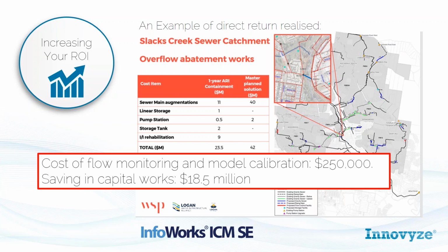Yep, thanks, Patrick. So I guess I'll just rewind a little bit. Queensland is a little bit behind the rest of Australia and the world. It traditionally has been, and the approach to sewer planning and network analysis has been based on the traditional peak wet weather flow approach. So typically 5 times average dry weather flow, and a static, steady state analysis of sewer networks.